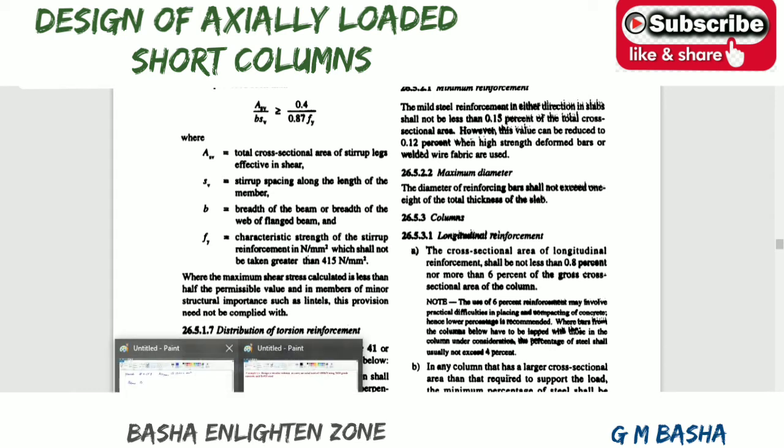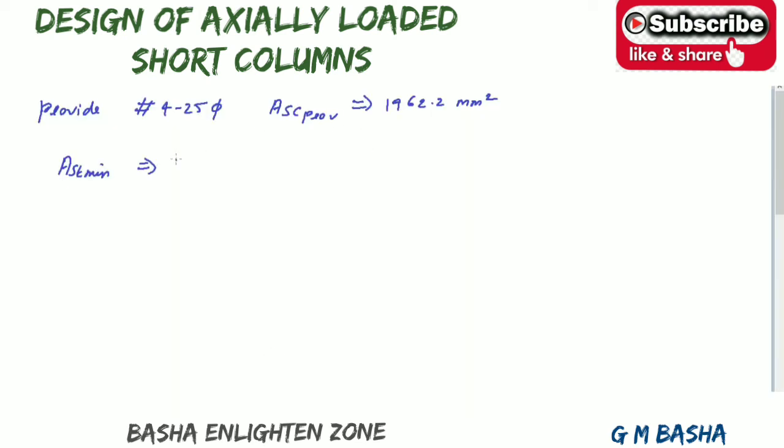So that is 0.8% of gross cross-sectional area, that is 0.8 divided by 100 into B into D. So here B and D will be equal, that is 420 by 420, into 0.8 divided by 100.